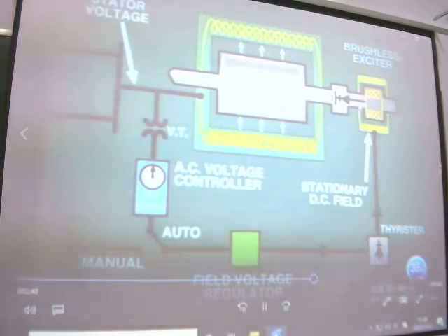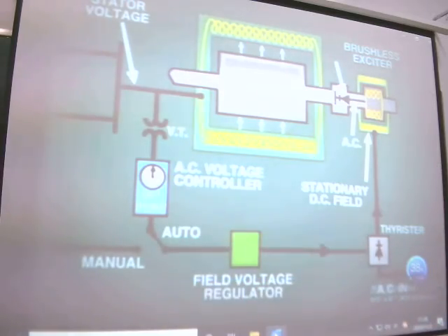The rotor winding produces AC voltage, and this is fed directly to the diode type rectifiers, which are built into the shaft. So we have, in effect, a rotating rectifier. The DC output from the rectifier is connected directly to the main rotor winding through leads which pass inside the shaft. There is no need for collector rings or brushes.